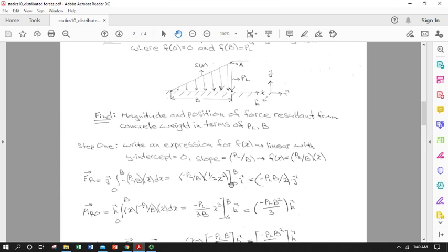And now it just depends on what fraction of this ramp we want to consider. And that's where our limits of integration come in. We could stop this integral at any x and get the force due to this bit or this bit, but we want the bit from 0 to b. So these are what are known as limits of integration, and we bring them back over in this expression.